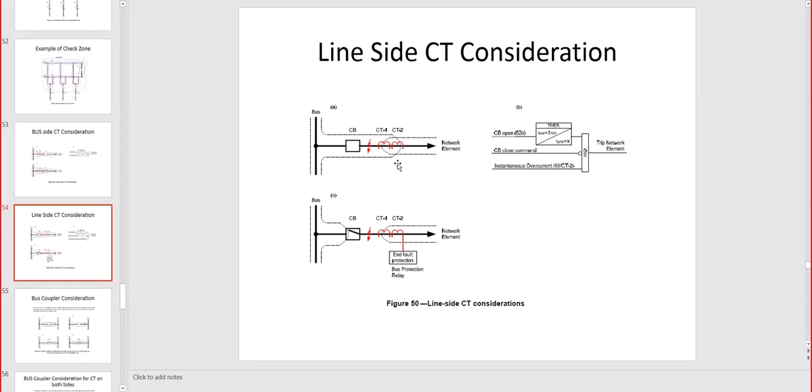You cannot have phase 1 and 2 close and 3 after 1 minute. That is unacceptable, because you create a huge unbalance and other protections will trip also. But that's how you identify breaker fault. Again, it is based on the current on both sides, voltage on both sides if you want, and also comparing the power poles 52 with the auxiliary 33 A or B. A in sync with 52, B in negate logic.